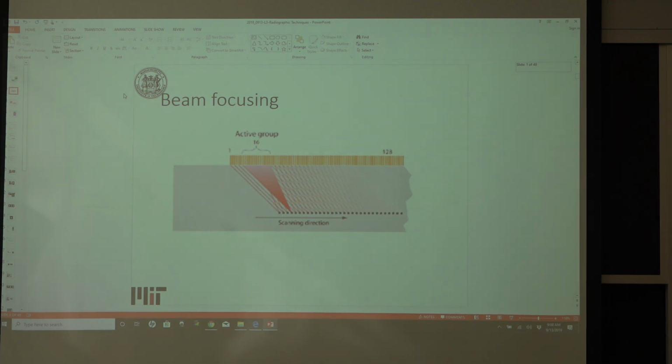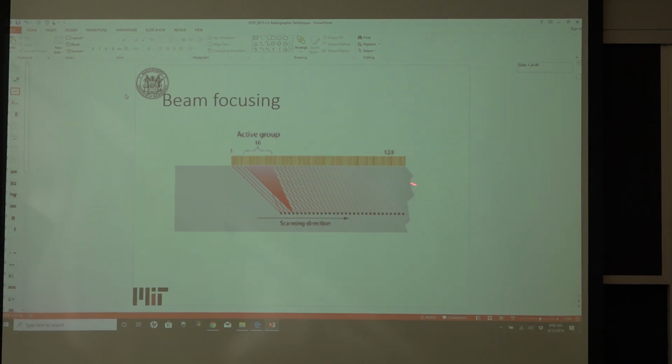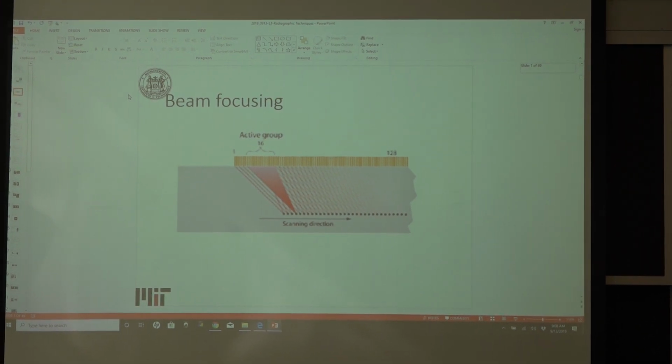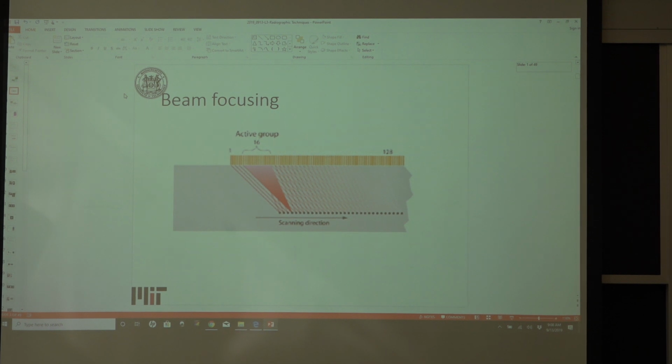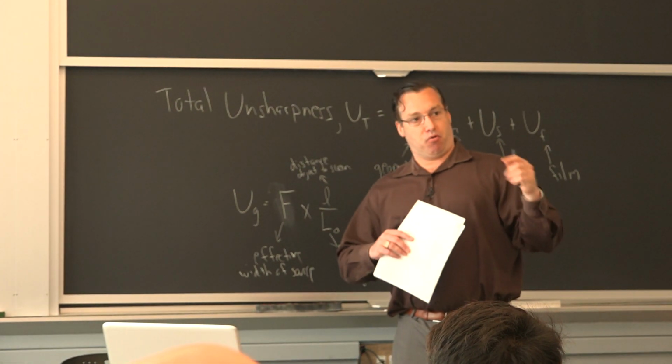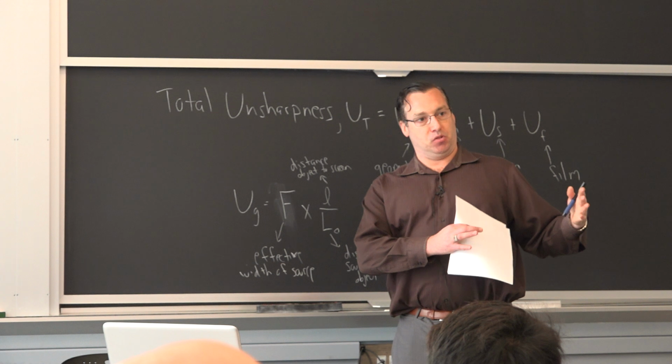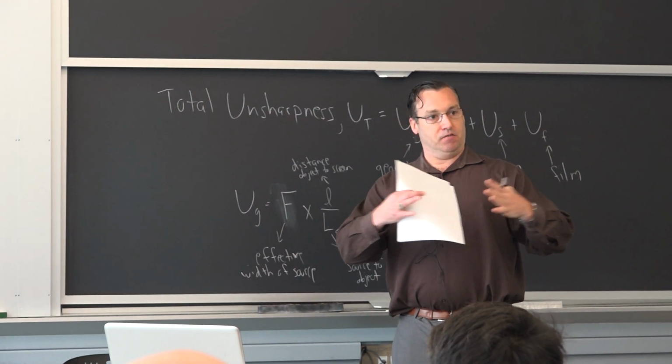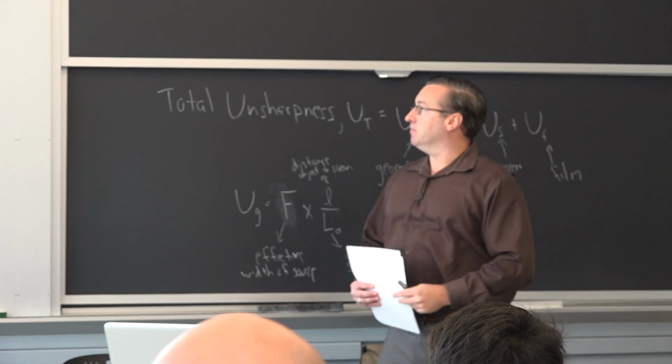Some of the commercial units have up to 128 elements. What it does is automatically use Snell's law, and it sends a time lapse that is programmed into the element for each active transducer. That way, when it goes into the program, it knows the time lapse between elements, and it gives you more data simultaneously.